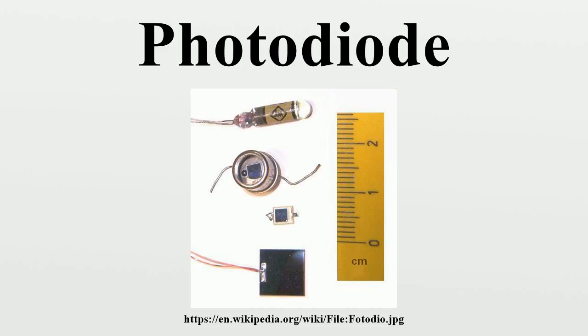Photodiodes usually have a slower response time as their surface area increases. The common, traditional solar cell used to generate electric solar power is a large-area photodiode. Photodiodes are similar to regular semiconductor diodes except that they may be either exposed or packaged with a window or optical fiber connection, to allow light to reach the sensitive part of the device.